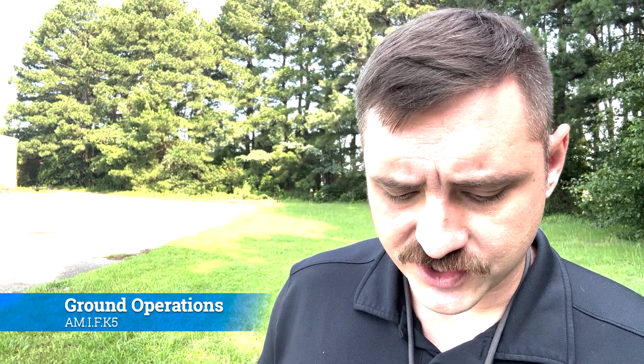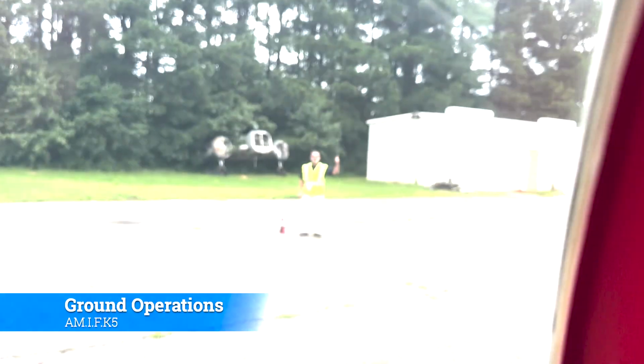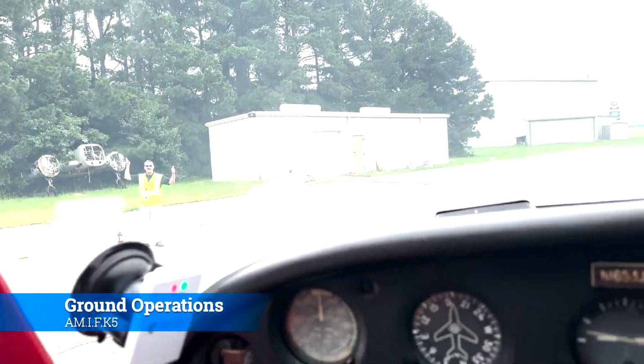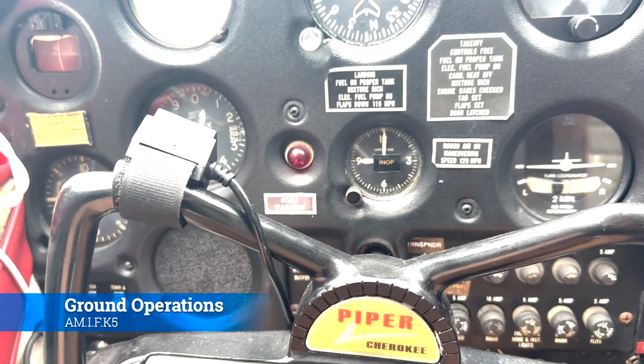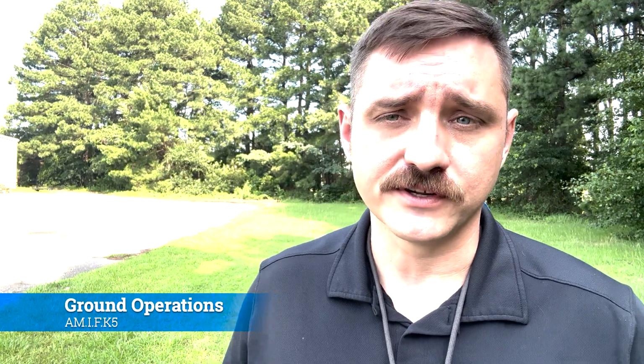Okay. Energize the starter, and after the propeller has made at least 2 complete revolutions, turn the ignition switch on. Now, this is kind of dated. Most aircraft don't work this way, though they could. But clear! What you will typically do is you'll have a magneto switch that says left, right, and both. You're either going to turn it to both and then press the start switch, and that will start it, or as soon as you hit both, there'll be another notch or a momentary switch that says start, and once it starts, you can let go and it'll go back to both, and you're good to go. It just depends on how the aircraft is configured, which is why the checklist is so important, because the checklist will be optimized to the aircraft that you're starting.